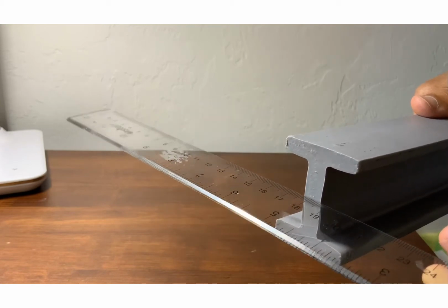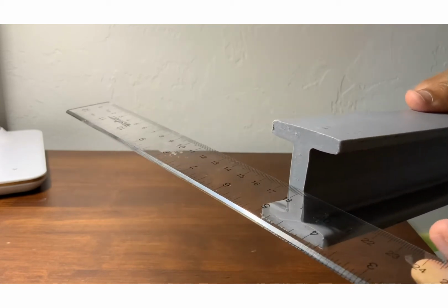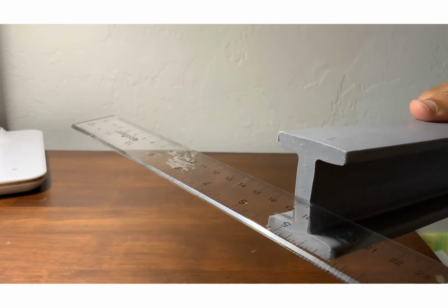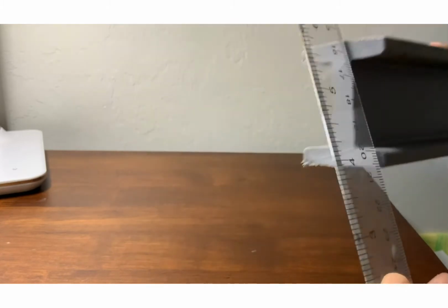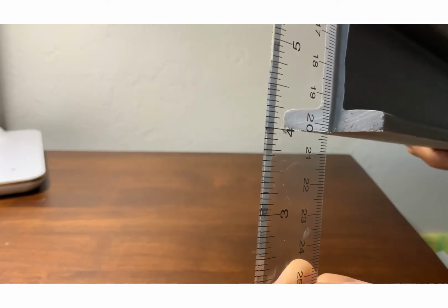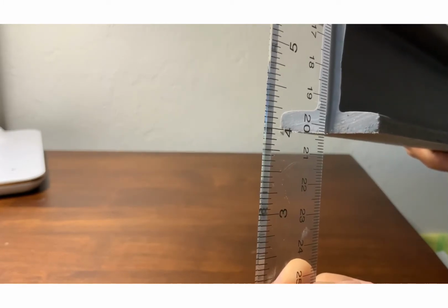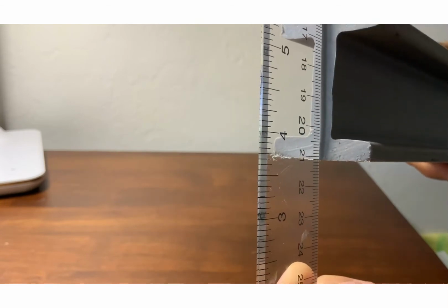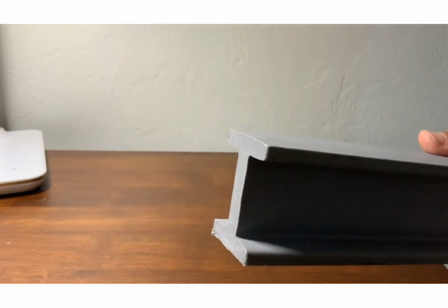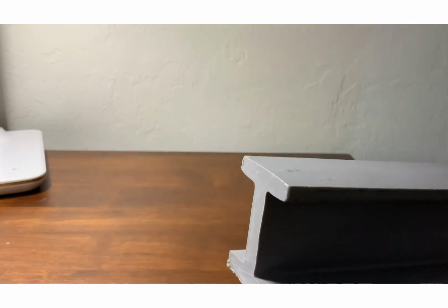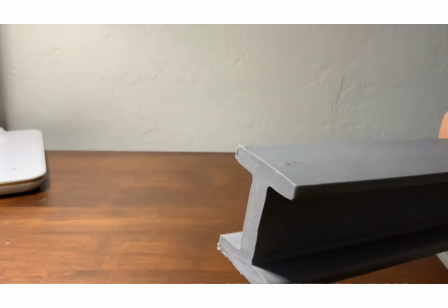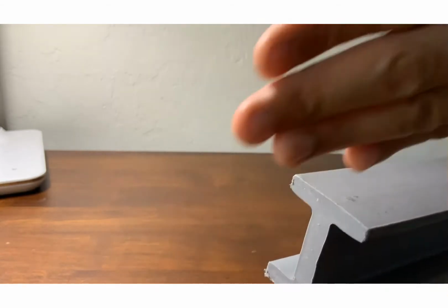The X axis goes through the middle, perpendicular to the web. The Y axis, in Appendix C, goes through the middle of the web, parallel to it. In the tables, you always see Ix, the area moment of inertia about the axis perpendicular to the web, always greater than Iy, the one parallel to the web, the vertical one.